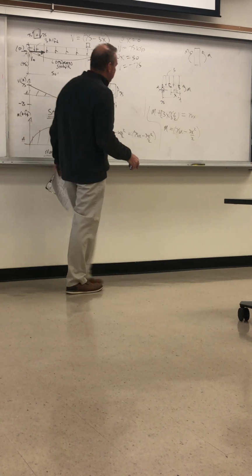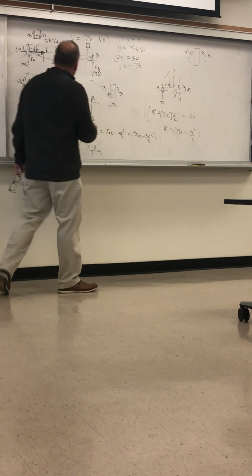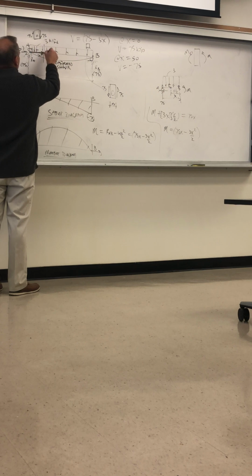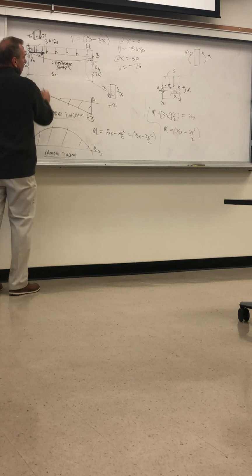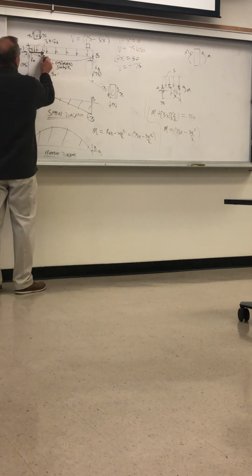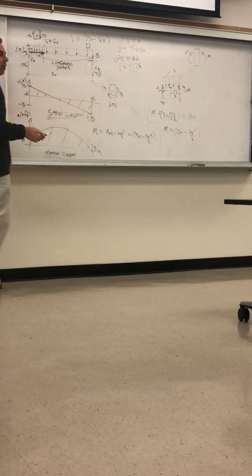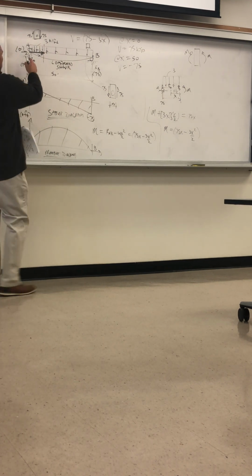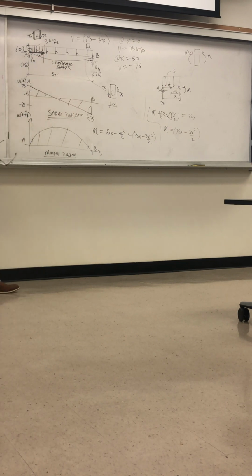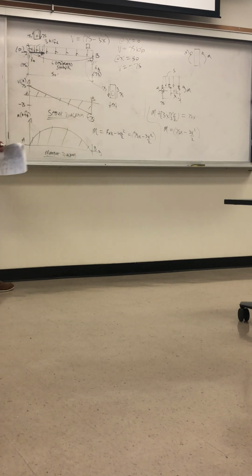Which is that. So I don't do it that way, but this explains it to you where it comes from. So I just say, it's just this times this minus the moment associated with this. This is the moment in the beam here, the same as this. And I'm saying it's 75 times x, any distance x, minus the moment associated with that distributed load. You have to take the distributed load, multiply it by x to get the total load down, and then half the distance. You could use calculus also and integrate that, but you get the same result. It's not needed in this case.